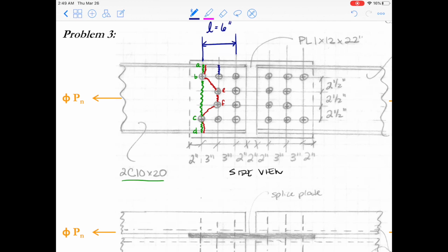There's the possibility, remember, whenever we go on a diagonal, we get to add a little bit extra to our net section area. So I'm going to consider the section in blue. The section in blue will go through 4 bolts in the cross section, across the width of the channel member there, the depth of the channel member. But it won't go on any diagonals. However,